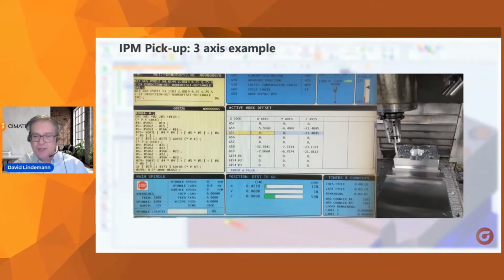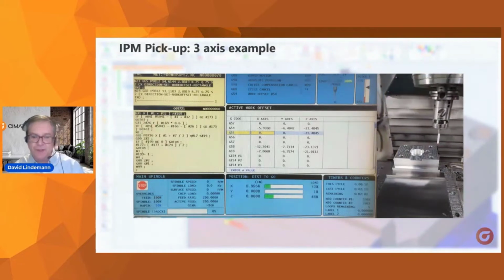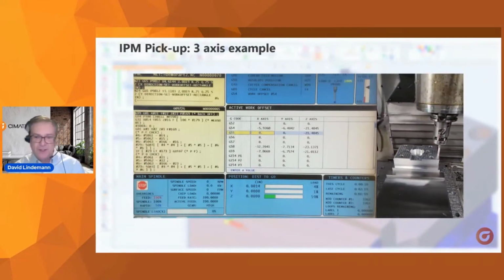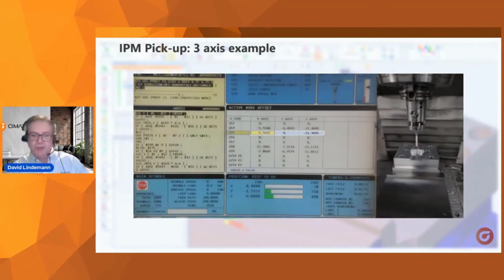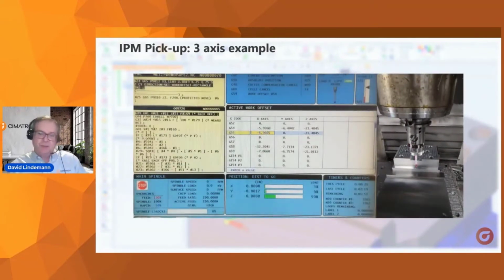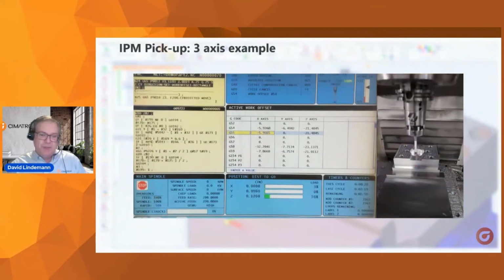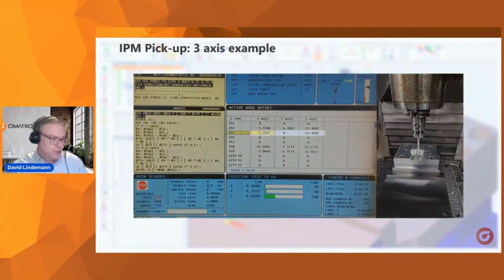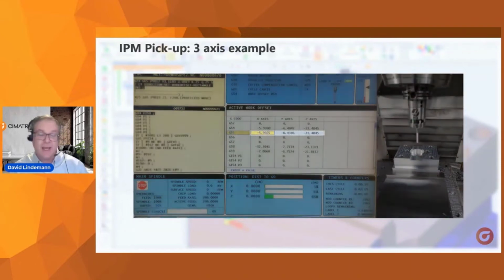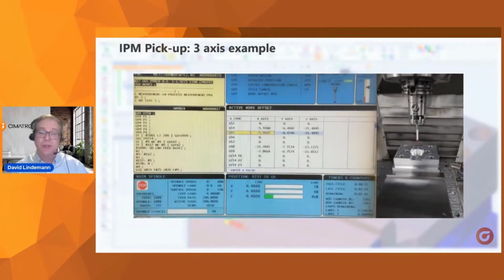And you can imagine how you do it now. Perhaps you use an edge finder to come along an edge and try to zero it out there, then dial it over. You're bringing your tool down to get your tool offset. You may be wiggling a piece of paper or a piece of shim stock underneath it until it traps it. Then you know you've got your tool offset. Very accurately here, we're using the probe to get that information. Now our G55 is ready for us to take our cut with.